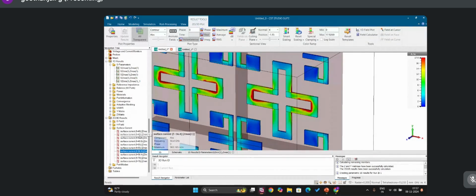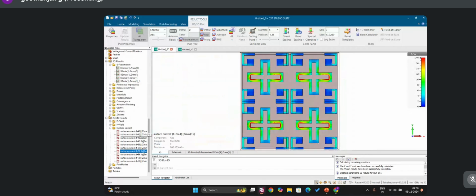If you are going for high frequency, like automotive radar or defense radar application, you have to go for the FCC allocation table to fix that particular frequency, and you can design the FSS on a conformal substrate. So it depends upon the frequency that you are choosing to design this FSS. I hope you are clear with the general idea of how to design the band stop and band pass FSS. So we will summarize.